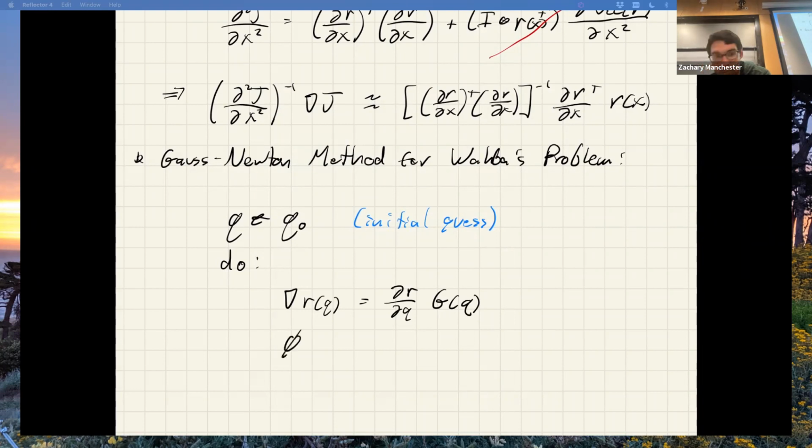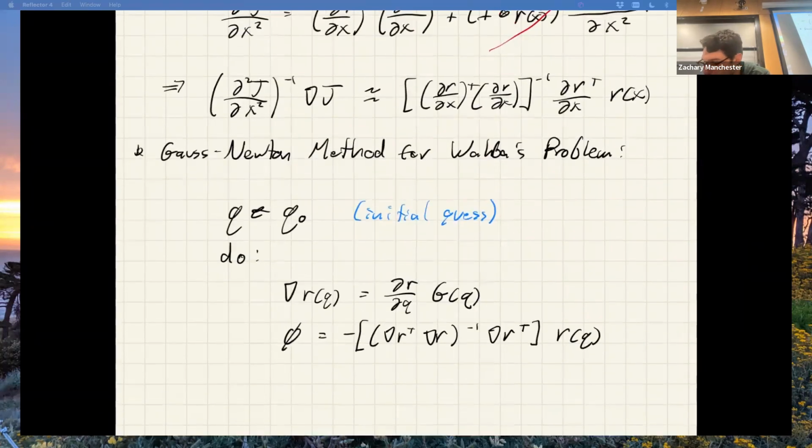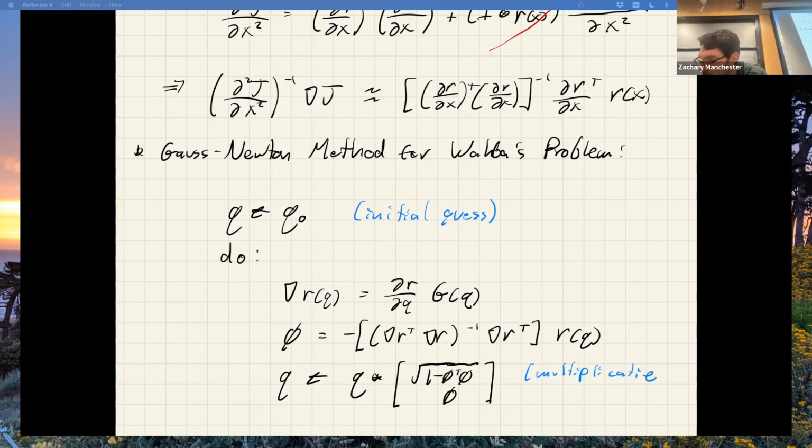So I do that. Now I'm going to compute my step, which is a Newton thing. We're basically going to compute all the Gauss-Newton stuff using, again, the stuff up there with the attitude Jacobian plugged in. Then when I update my Q, I'm going to do the multiplicative thing instead of adding, like we talked about. I take the phi that I get out, assume it's the vector part of my quaternion, and multiply it on. Multiplicative update.